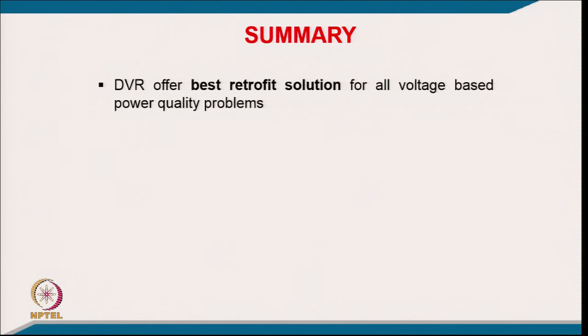So, now we would like to summarize this series compensator or DVR. DVR offers the best retrofit solution for all voltage based power quality problems. We discussed already the many problems of voltage compensation like voltage sag, swell, voltage fluctuation or imbalance, and voltage harmonics. So, all we have considered here.